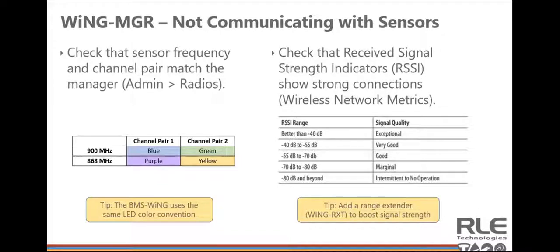To shift gears a little bit here, looking at the wireless or Wing Manager, the wireless sensors and things like that, there's a few things you'll want to keep in mind when setting those up. First off, the Wing TH can do dew point calculation, but it is not default to show up on the home screen. You do have to enable that through the menu. So if you are looking for dew point, specifically in, say, a data center or other place where that is a critical thing, make sure you enable it. It's a pretty simple on-off toggle in the settings there.